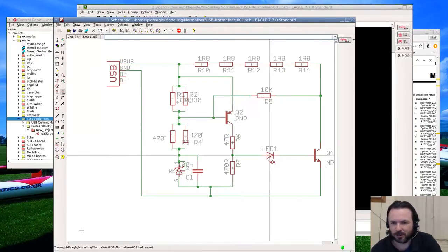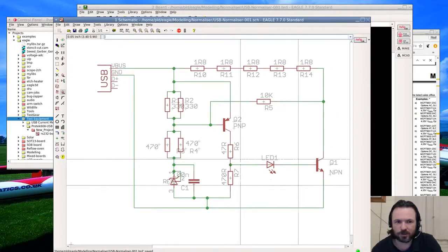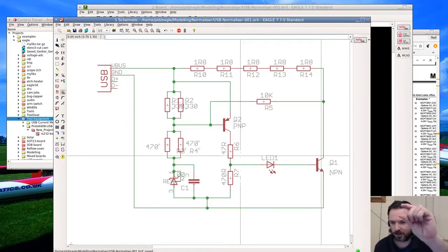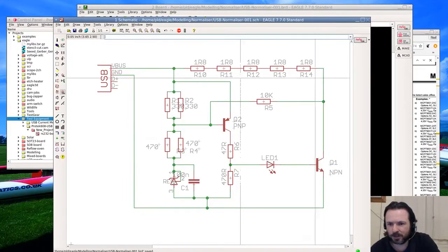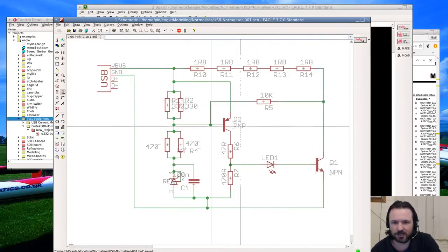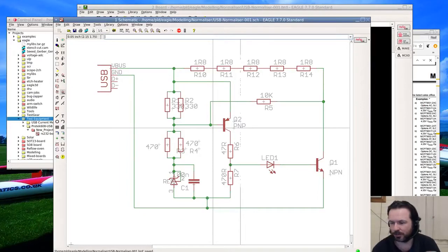And they'll get split, and there'll be enough of a voltage even after this LED, which will be about a 1.8 volt drop, to subsequently turn on this transistor here, which will then again, you'll get the squeeze effect between the collector and the emitter, 0.6, and the current will start flowing through these resistors, which are just 1.8 ohms. And what happens then is, with that closing, it pulls this feedback line here down, which subsequently pulls that base down even further, which keeps the transistor conducting even stronger,